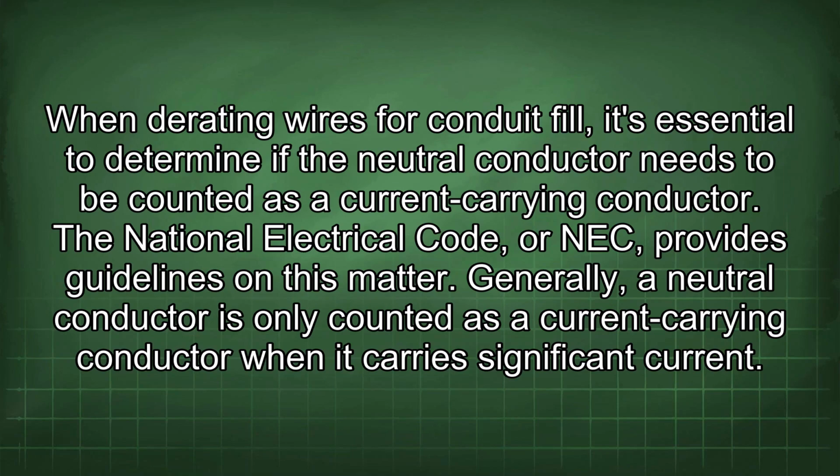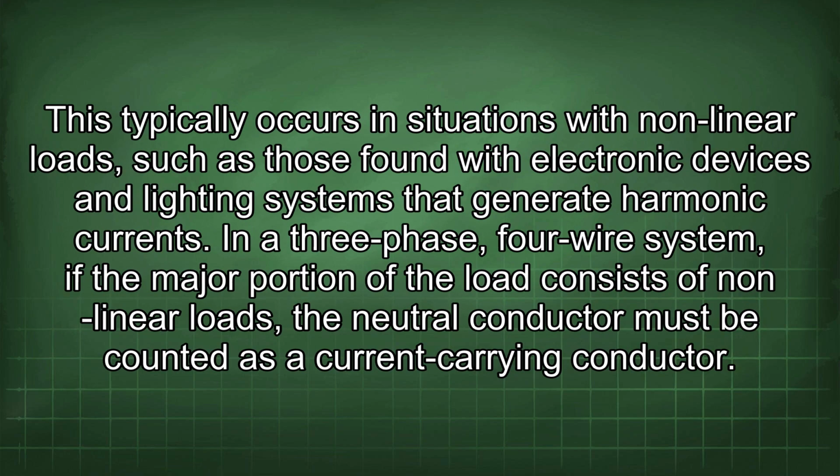When derating wires for conduit fill, it's essential to determine if the neutral conductor needs to be counted as a current-carrying conductor. The National Electrical Code, or NEC, provides guidelines on this matter. Generally, a neutral conductor is only counted as a current-carrying conductor when it carries significant current. This typically occurs in situations with nonlinear loads, such as those found with electronic devices and lighting systems that generate harmonic currents. In a three-phase, four-wire system, if the major portion of the load consists of nonlinear loads, the neutral